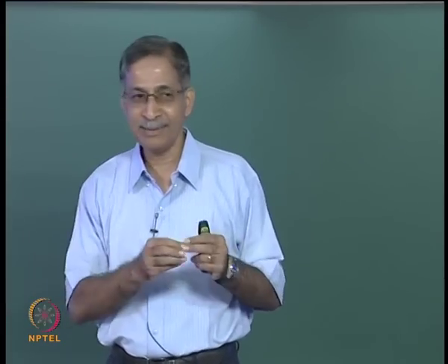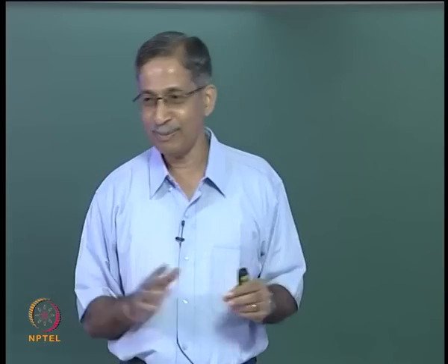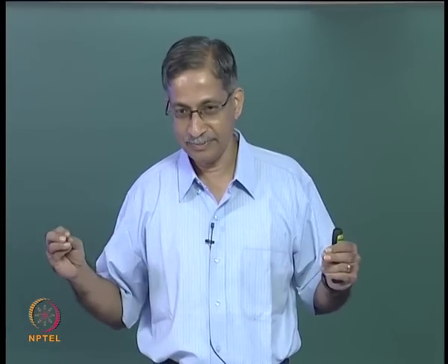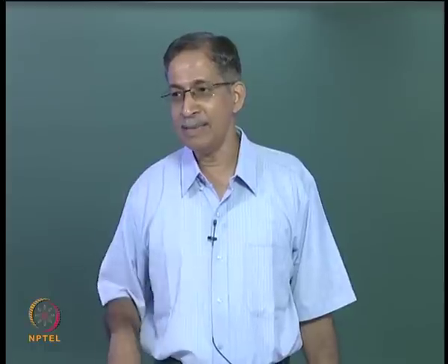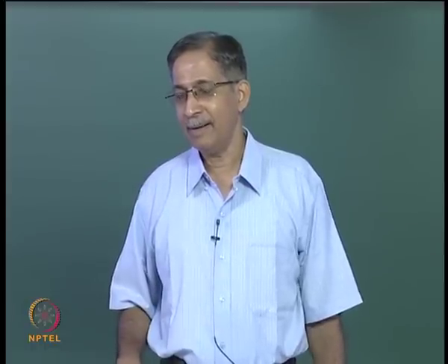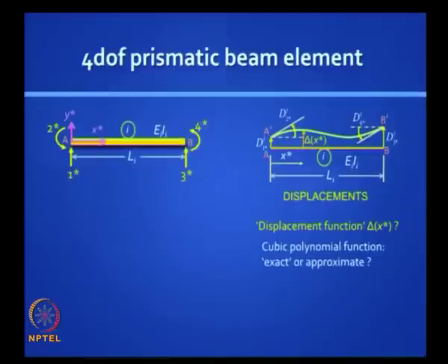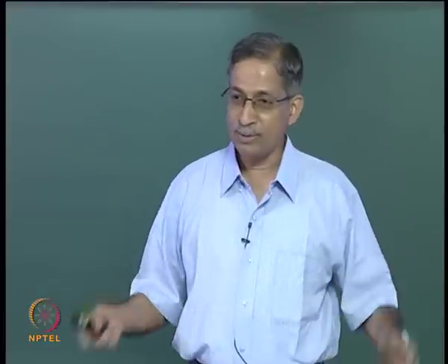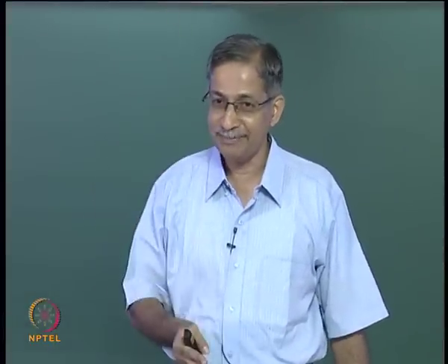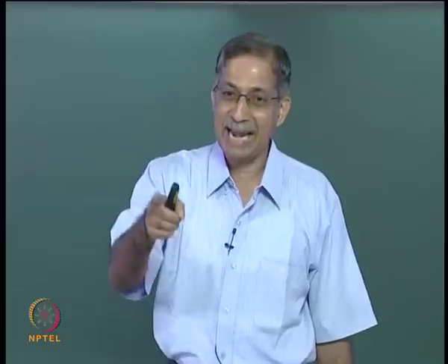So we are trying to get rid of intermediate loads in all displacement methods through equivalent joint loads. So your bending moment can have two different values. Here also you have F2 star and F4 star, they need not be the same. So you have a linear interpolation between the two end moments to get the bending moment at any section. Can you use that?